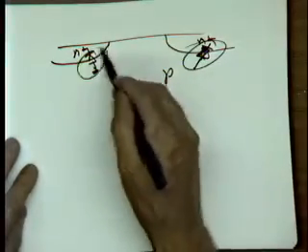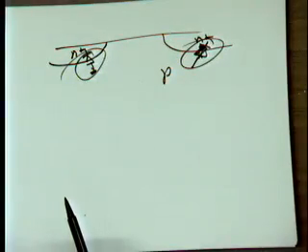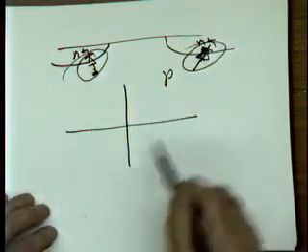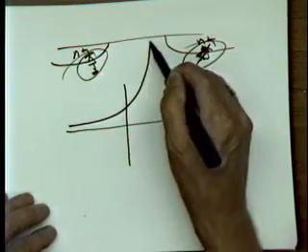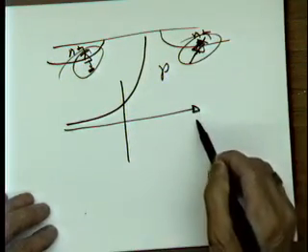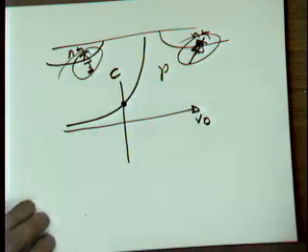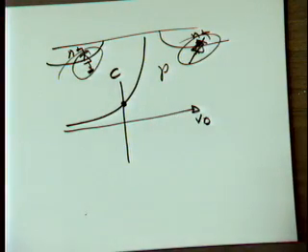So diodes come with capacitance, depletion capacitance. Actually, it's pure depletion cap. Very nonlinear, and we know the diode capacitance looks like something like this, if this is the voltage over the diode, and this is the capacitance. This is the capacitance when you have 0 voltage over the diode.